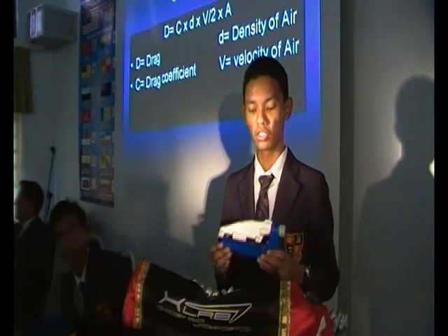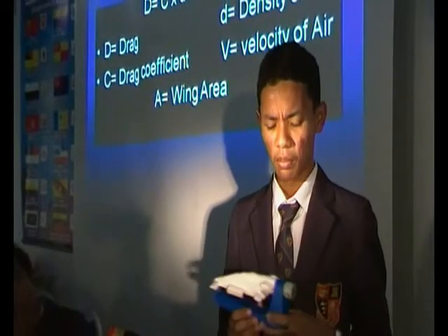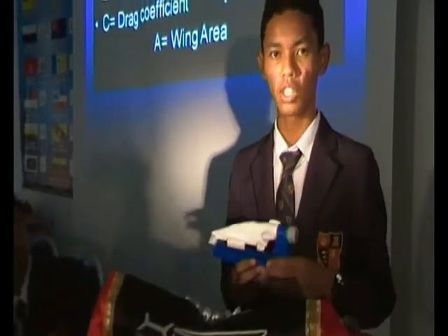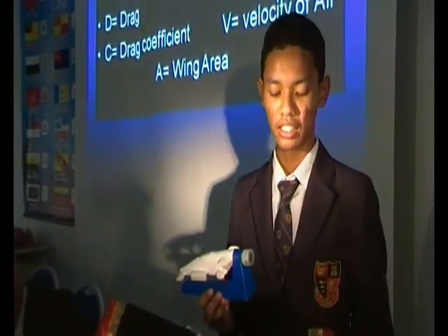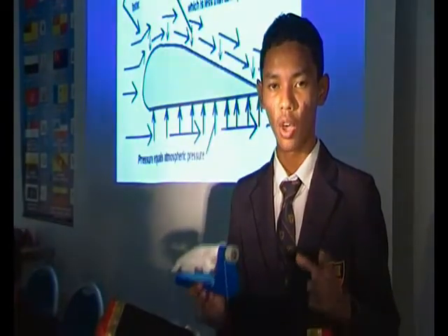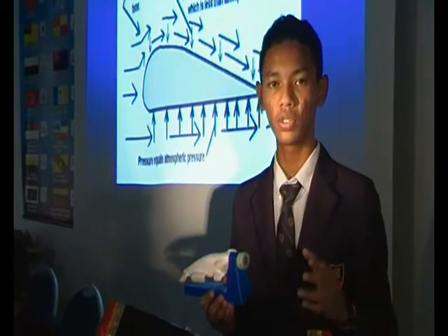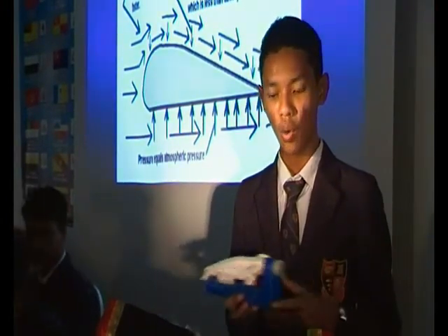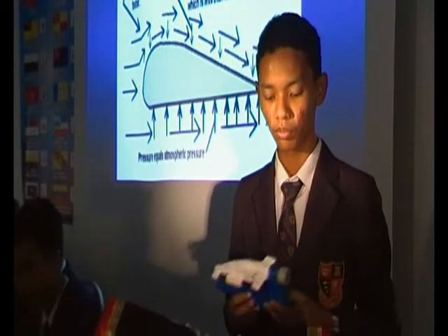The 3 main areas where drag affects the car are the front wing, side pod and rear wings. Besides that, drag also will slow down our car by pulling the back of the car. This is because a vacuum is created by turbulence. The next one is Bernoulli's principle. Bernoulli's principle states that when the speed of the fluid increases, the pressure will decrease and vice versa. Therefore, we designed our car's wings according to Bernoulli's principle.